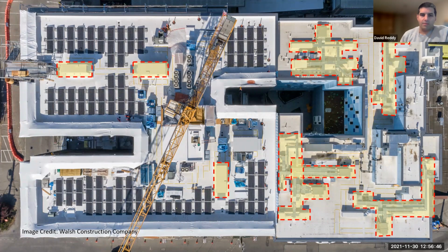That is our recommendation, because it also allows you to comply with the energy code, the C406 section of the energy code, by providing balanced ventilation with heat recovery for the corridors as well. That's not required by code for 2018, but it's an option, and you can get credits towards compliance by doing so. So if you're already putting these centralized ERVs in your project, I would strongly recommend considering ventilating your corridors with them as well. It's energy efficient, you get compliance credit, and it reduces the number of pieces of equipment.